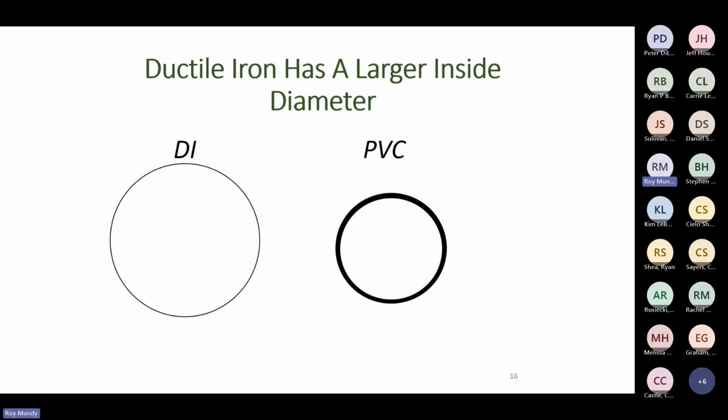If you have a larger inside area for the pipe, you can have a lower velocity to obtain the same Q factor. So on the other hand, if you have a smaller inside diameter or area of pipe, and you need that larger V to equal that same Q, then to increase the velocity in the pipe, typically you have to have energy applied,